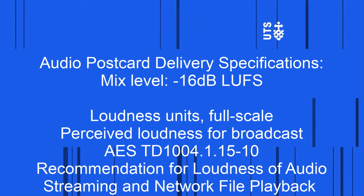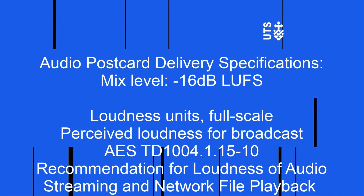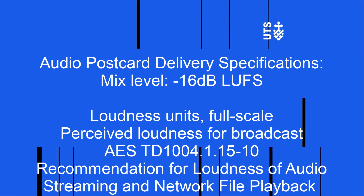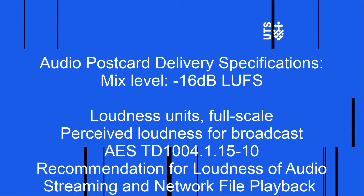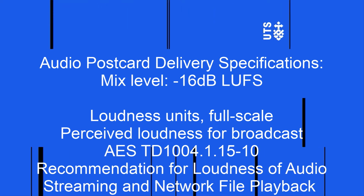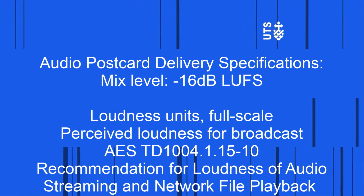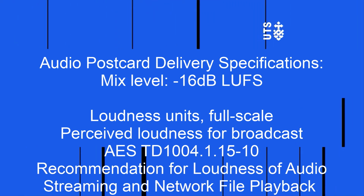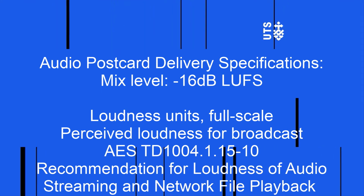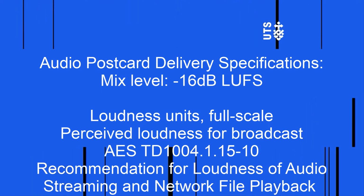The Audio Engineering Society recommend setting the loudness level of mixes targeting streaming media to -16 dB LUFS with a peak level of -2 dB. To make this measurement, we need a special meter, but we also need to control the dynamic range of our mix so that it does not exceed -2 dB. For this, we need a dynamic range control device called a program limiter.